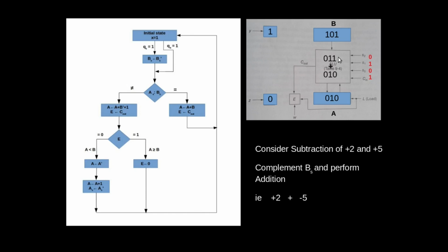Then ALU will take the 2's complement of this magnitude part, because we have to take 5 as minus 5 in 2's complement, because ALU will perform only using 2's complement arithmetic. That is why ALU will take the 2's complement of this 5 to make that a minus 5 inside the ALU, then perform the operation.